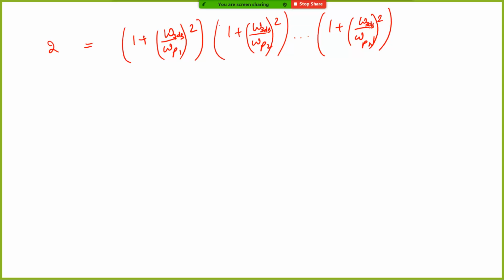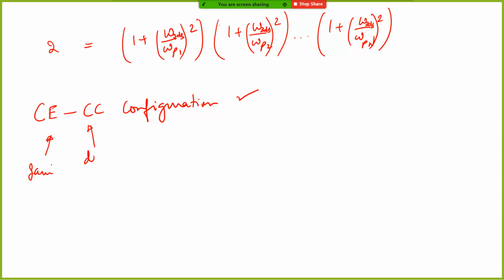Now the other thing that I want to talk about is that we have already looked at one instance of our cascaded amplifiers. You have already looked at the common emitter with common collector configuration. I think you have already done this in the lab as well, right? We saw the necessity for this. If you want to drive a load impedance which is low, you have this providing the gain and this providing the drive. Okay, and you've already done this in lab.